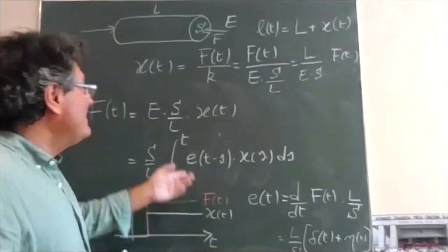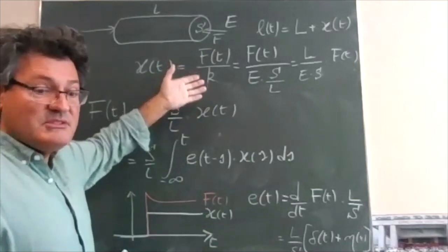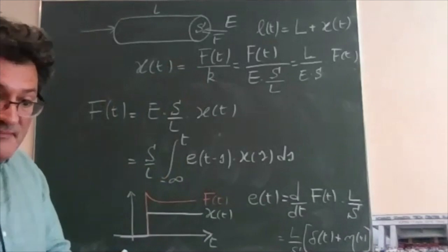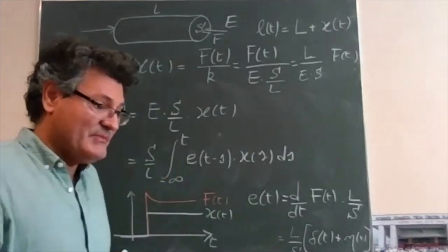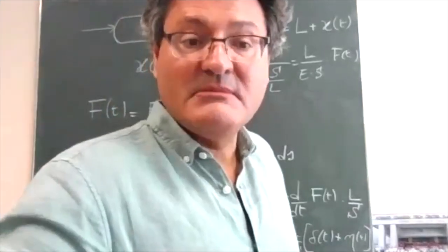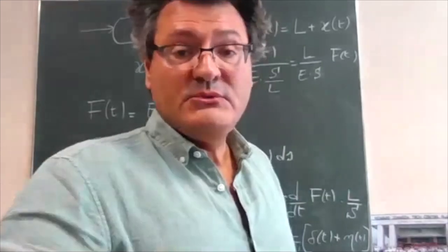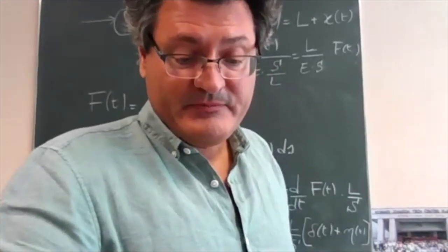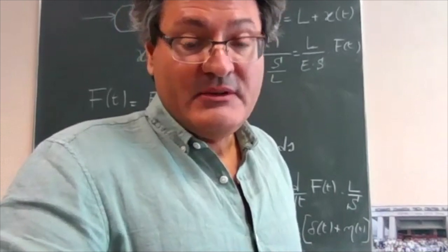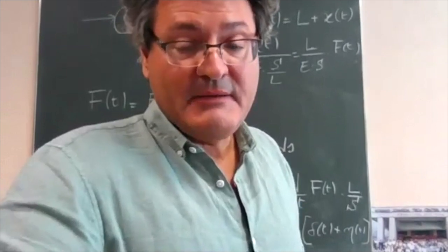And the imaginary part enters into the imaginary part of the response of your system. And here we have the origin of thermal noise and the way we calculate the thermal noise in the mechanical system. Now it's time to introduce one of the main actors of the thermal noise calculations in gravitational wave detectors, which is the loss angle.